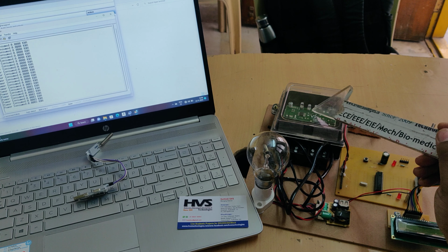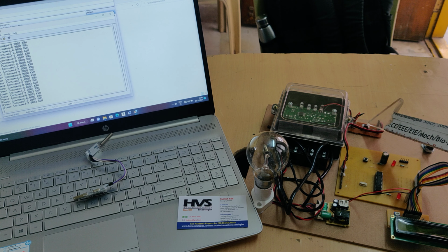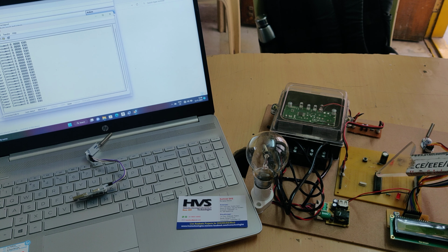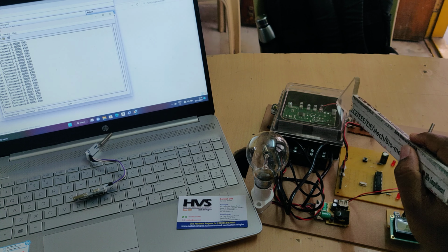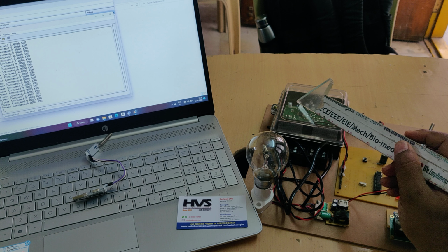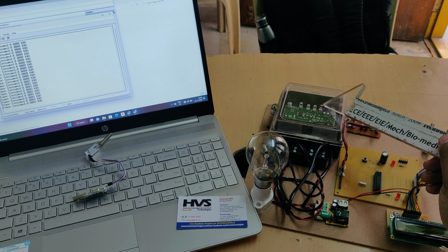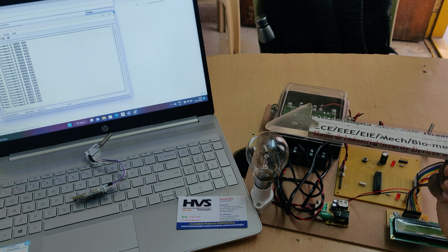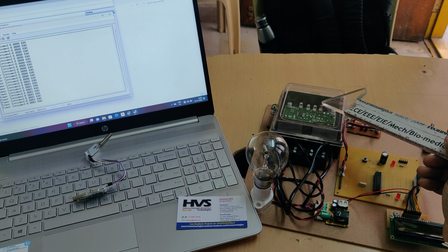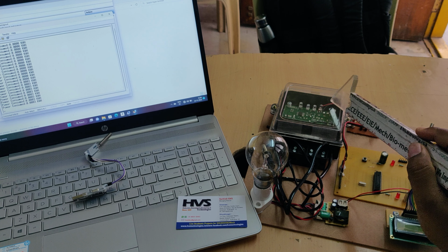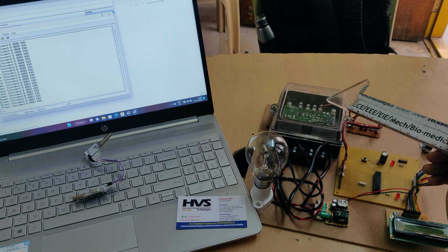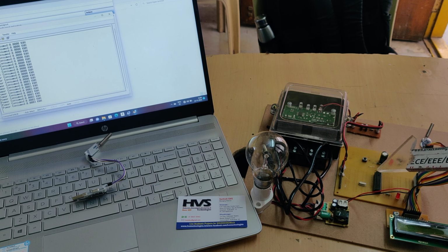So we have interfaced this current meter through the optocoupler PC817 IC to the A4 pin of our microcontroller. Here the optocoupler's purpose is this: on this current meter we can see these 4 LEDs. In that, the first LED is a power LED indication and the last LED is a wattage current LED indication. Whenever a heavy load is connected on this meter, the blinking rate of this LED increases, becoming faster. Means if it blinks slowly, low load; fast blinking, high load. So based on the blinking rates, our controller will calculate that.